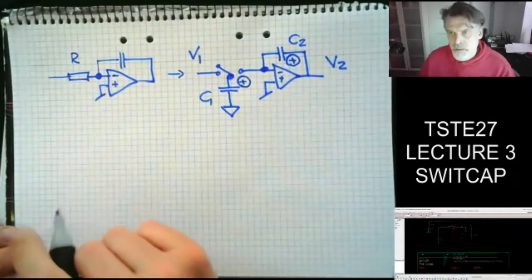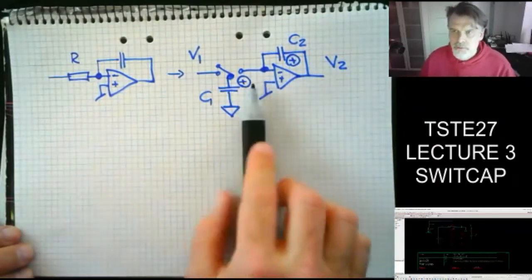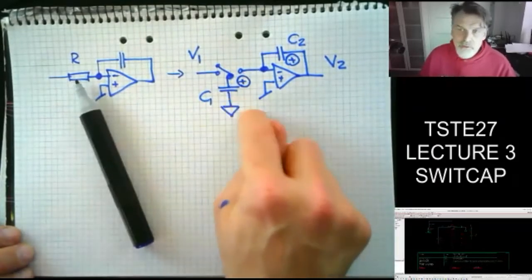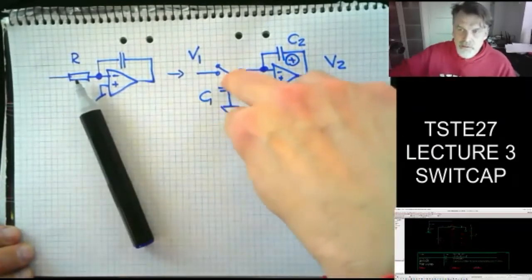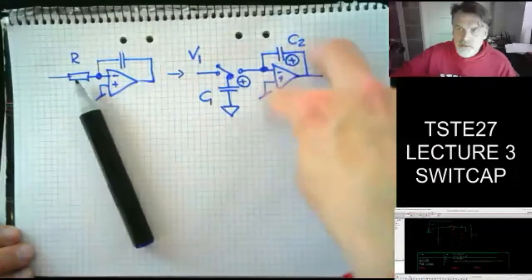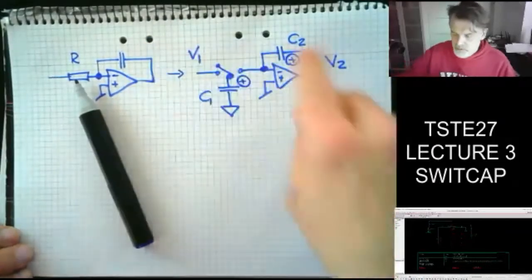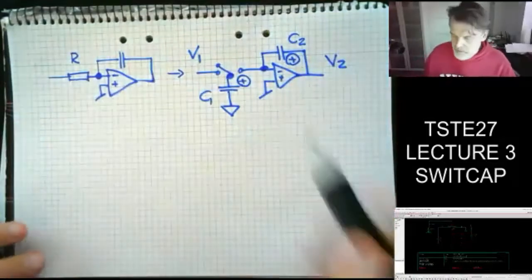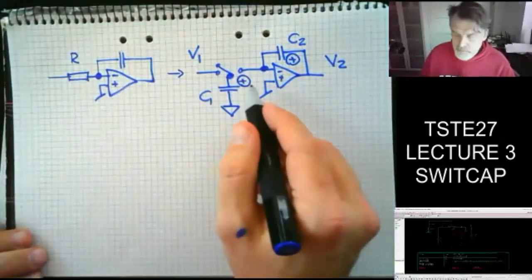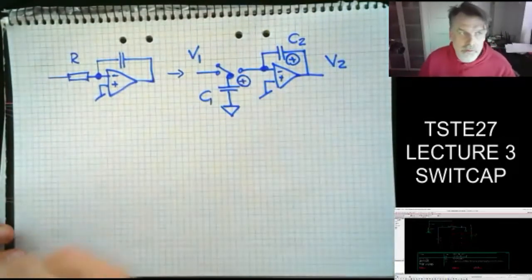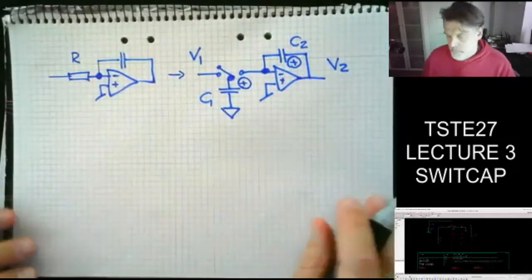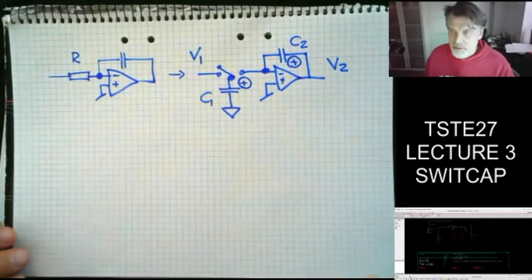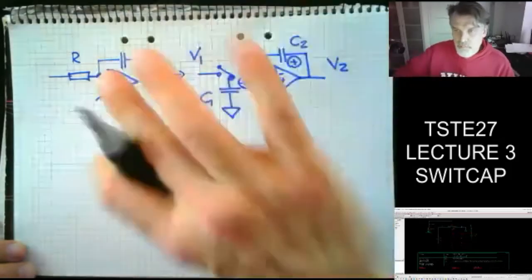and towards the output here. Why do I do that? Well, that's because we have switches now. So assume I could actually add a switch on the other side of the cap, and then, hypothetically, I could more or less connect the capacitor wherever I want into the network. I could have two cables connecting more or less anywhere. And that's important, to keep the direction in order when we do our charge preservation analysis, because then suddenly we could have a minus coming into the equation because we're sort of flipping the capacitor.